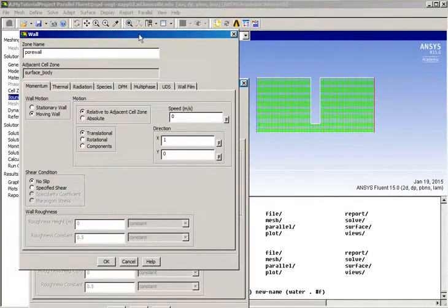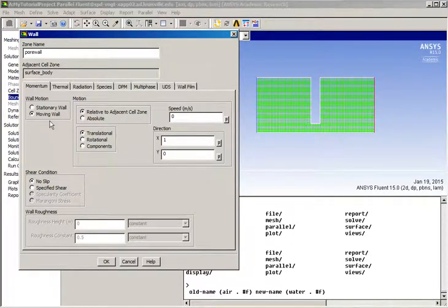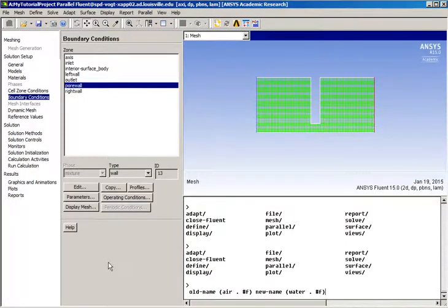Okay, and in an add-on to this tutorial, what I'd like to do is add a non-uniform velocity, but right now, let's just put in something in the X direction this way, horizontally. We got to see in the meshing panel that X was this direction. And so our vector for this direction is going to have 1 for its X component and 0 for its Y component. And speed, let's put it at a millimeter per second, 0.001. No slip, translational. And, well, we don't really have moving cells on it, but we can put absolute. Okay. And that's the only thing we have to do.